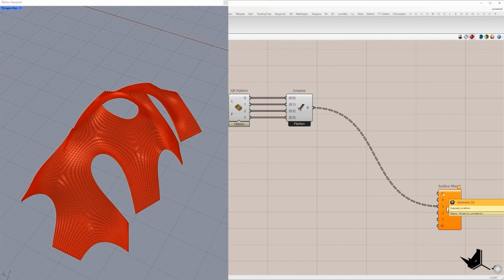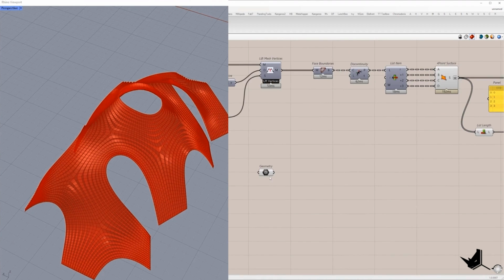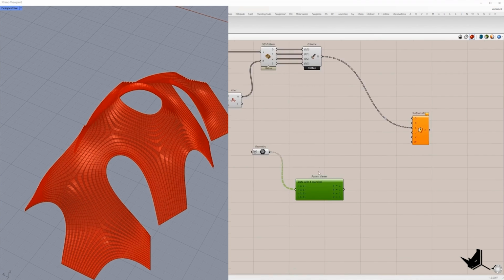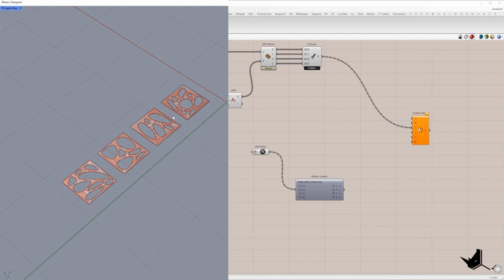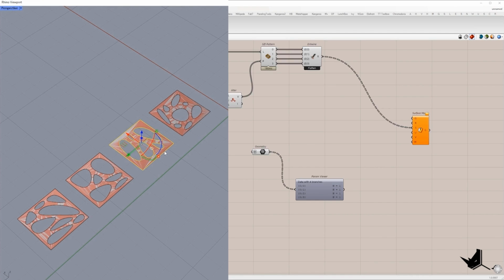The first one is Geometry 2D form. Here we get the Geometry 2D form. But keep in mind that we have 4 branches, so each of these tiles should be placed in a different branch. There is one more step that we need to define, because I don't want to map them in the same orientation. Maybe sometimes I want to rotate this one by 90 degrees, this one I want to rotate by 180 degrees, and this one will be rotated, let's say, by 270.